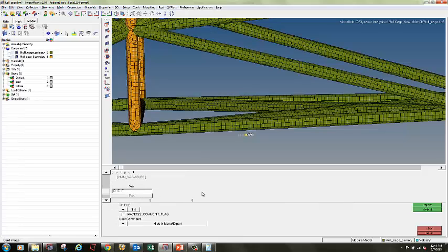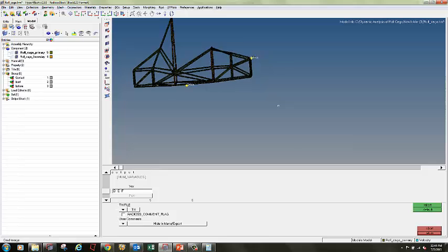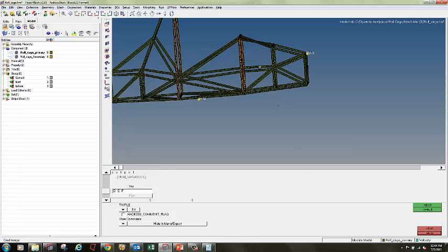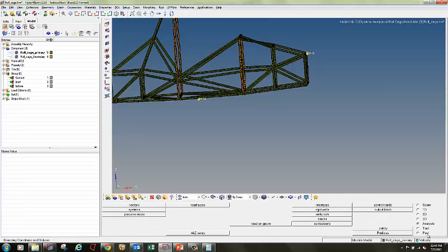Now we will get three outputs, one for this component, one for this component, and one for combined. If I want to see the deformation and stress values for a particular component, I can see that also, and I can see the combined also. That's why I requested an output request for all these things, and I will click return. Again I will click return.